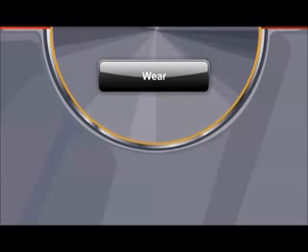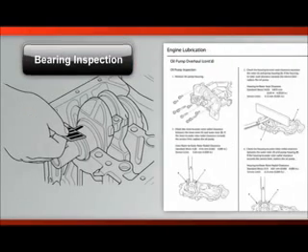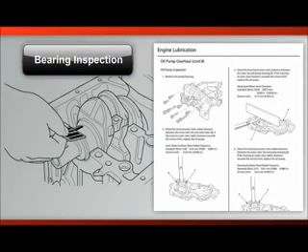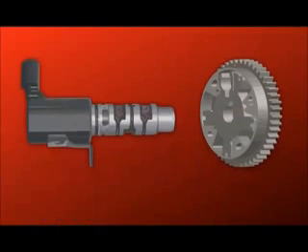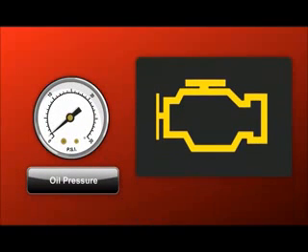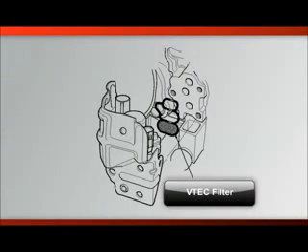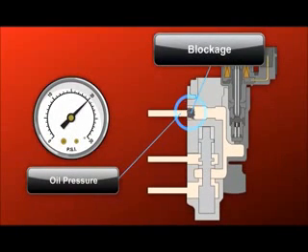As we stated earlier, oil pressure also drops as internal engine components wear. Wear creates excessive clearance, reducing resistance and allowing oil pressure to bleed away. Our service manuals include engine inspection procedures for bearings and oil pumps. Low engine oil pressure can cause VTEC engagement problems or VTC position faults. If overall oil pressure drops, these faults may cause the PCM to set a DTC. The VTC or VTEC solenoid filter screen can also illuminate the mill. Sludge or other blockages can isolate the VTEC system even when overall system pressure is good.